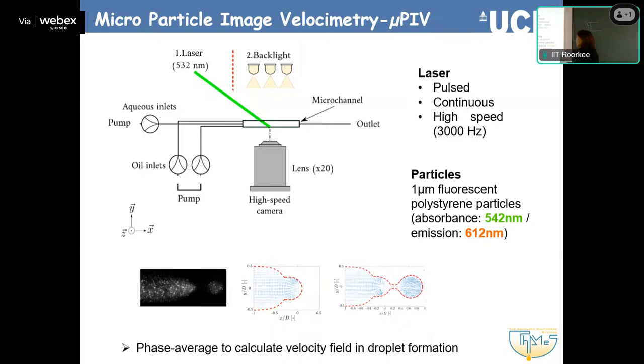There are variations. If you don't have enough particles, then you trace individual particles, and that's called particle tracking. Because in actual PIV, you don't try to see the actual particles, you get grayscales. So the algorithm doesn't look at specific particles, it looks at the grayscale of the image and how that translates to the next one. By getting these two frames, you get information on velocity profiles. That's why it's called particle image velocimetry. We measure velocities.